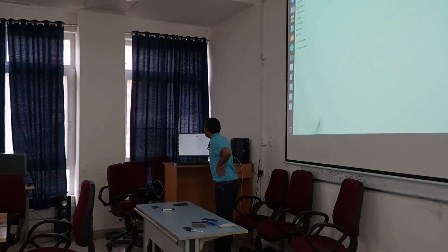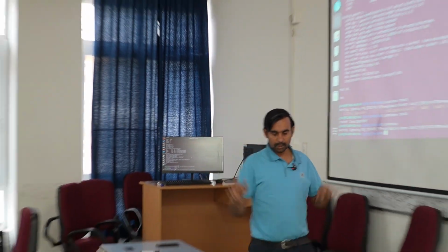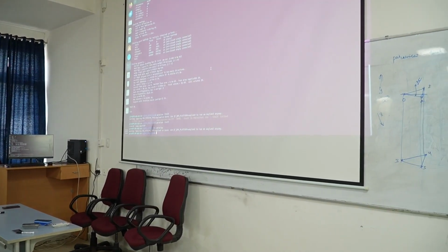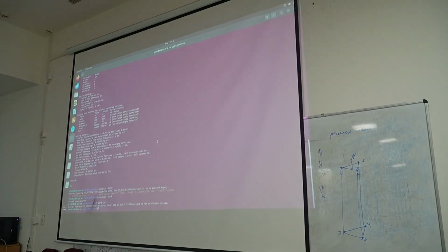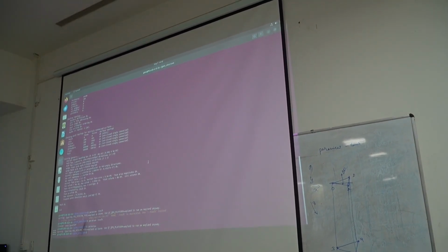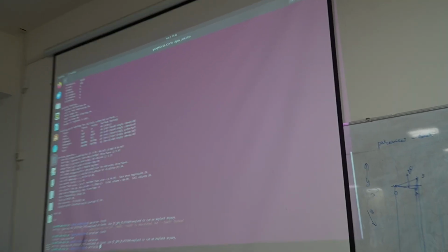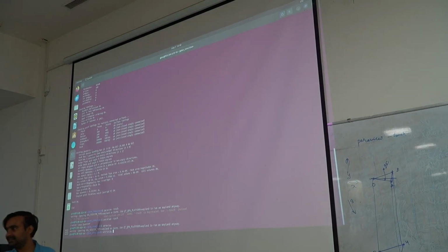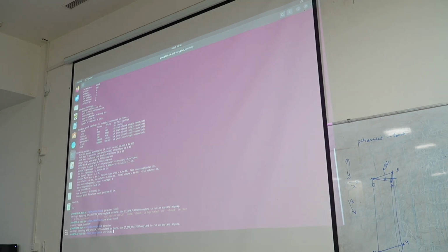Now I will again go to the terminal. If you have not closed the previous terminal, please open it. In case you have closed it, you have to open the terminal again and first write the OF7 command. In this terminal, I will now write the setFields command. How do we write it? setFields, with small s, e, t, capital F, and then ields. Typically, if you simply write set with a small s and capital F and then press tab, it will show the full command.